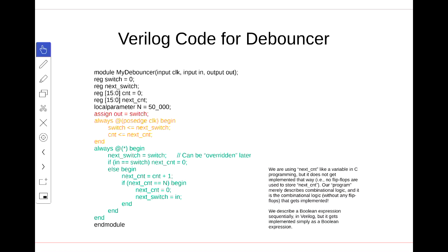Roughly, and this is very inefficient, one way that Quartus could work is this function, all it does is put in different possible inputs, computes the answer, and comes up with a truth table. And then, given that truth table, it goes off and implements that truth table using logic gates. That's the safest way of thinking what Verilog does.